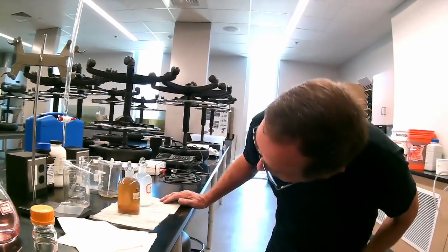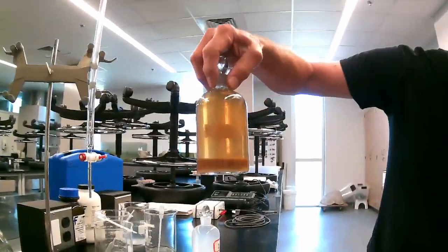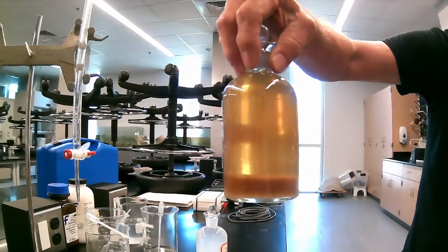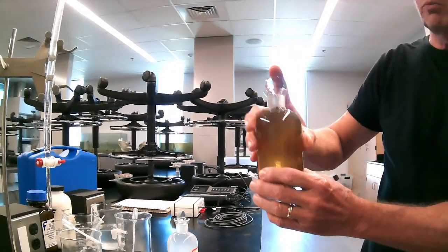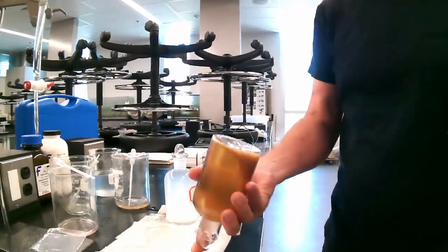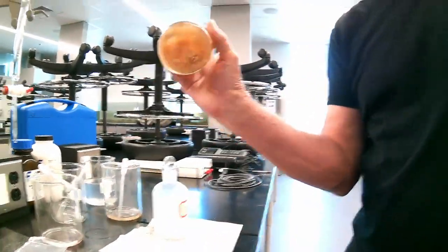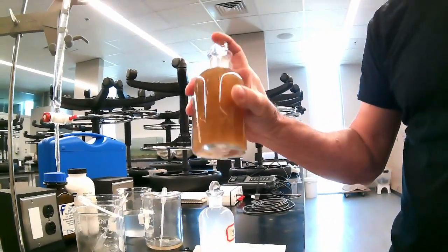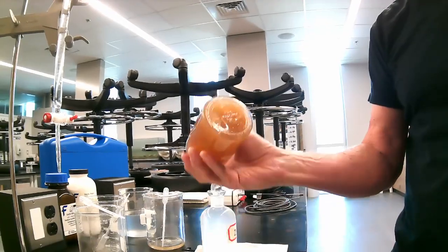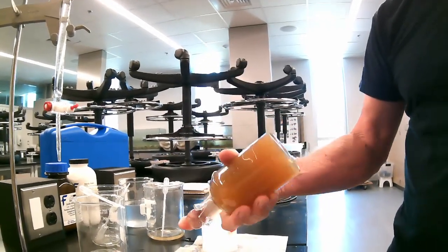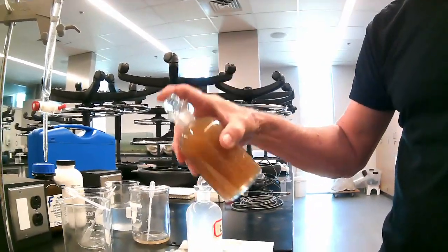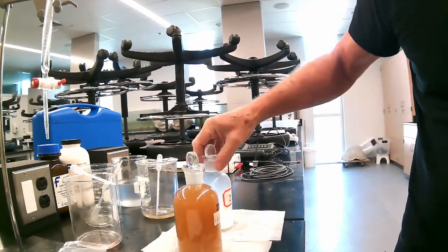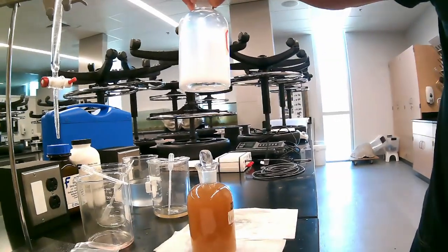Okay, so we'll let that sit for just a moment. You can see this one's pretty well settled out. The flocculant's all gathered up at the bottom. And once it reaches that point, you do it one more time. You roll it around to get that last little bit of oxygen in there. You want to get all of it. Remember, if you do this correctly, you can measure every single molecule of oxygen in that bottle. Give that one a little more time, but you can see it settling out too.